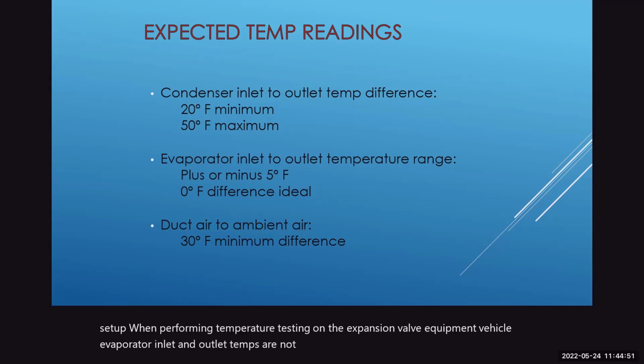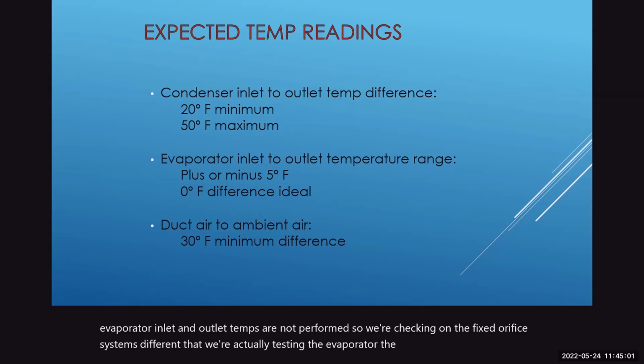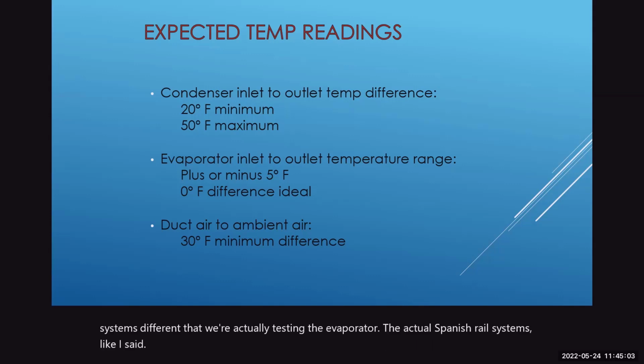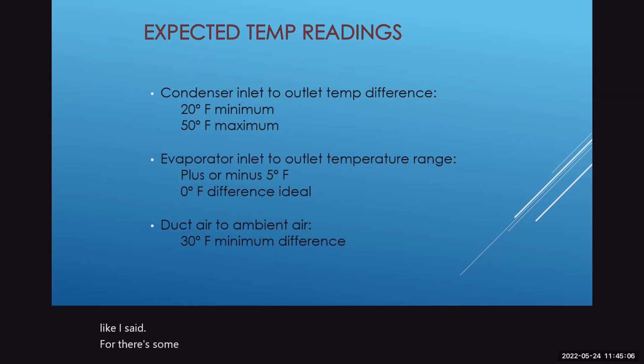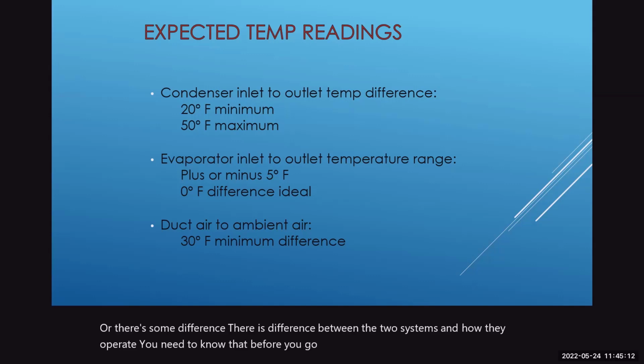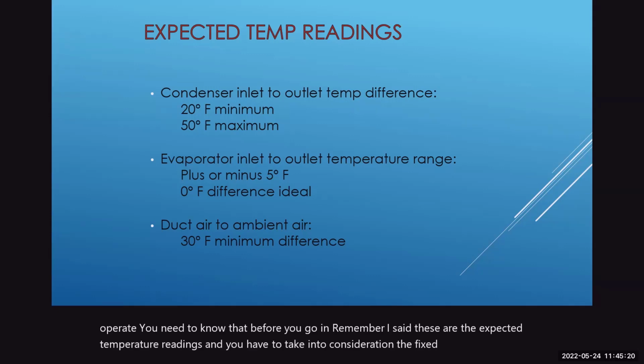So we're checking fixed orifice systems differently than we're testing the actual expansion valve systems. Like I said before, there is a difference between the two systems and how they operate. You need to know that before you go in. Remember, I said these are the expected temperature readings, and you have to take into consideration the fixed orifice difference from the expansion valve systems.